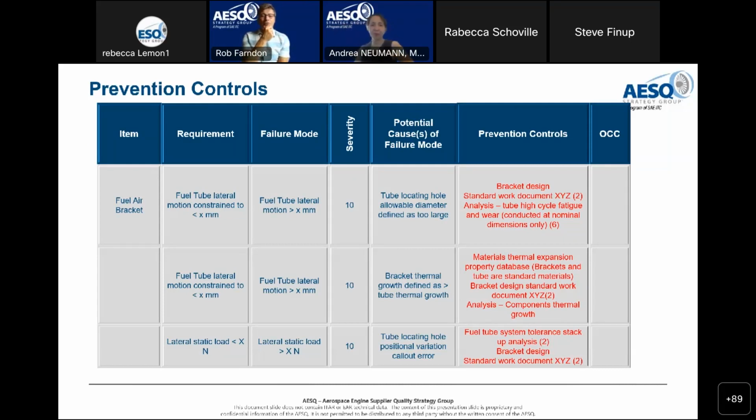So are there functional causes for failure? Not in the context of a DFMEA. That's not the mindset. The causes of failure in the DFMEA are the way the design could fail, not the way the component could fail. So a failure mode in the context of the DFMEA is the way I fail to achieve a requirement, right?